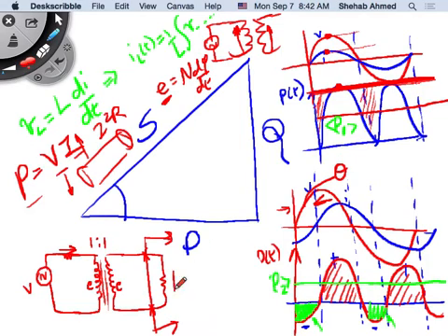Even if I have a resistive load, my load is purely resistive, is the source supplying only the resistive load? No, it's supplying the transformer and the resistive load, right? So this magnetizing branch is consuming the reactive power that's in the system. The reactive power in the system is something that, after you set up the magnetic field and you collapse it again, right? When you collapse the magnetic field, assuming there's no resistance in the path, what happens is that power goes back to the supply.